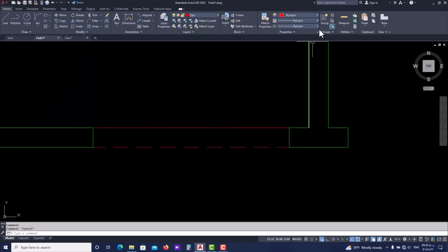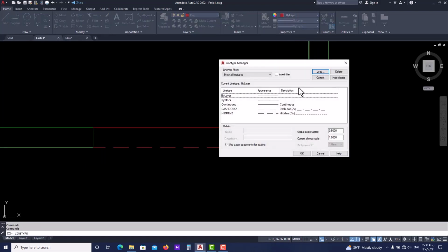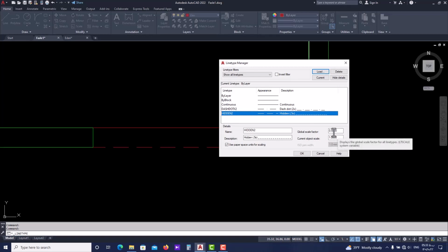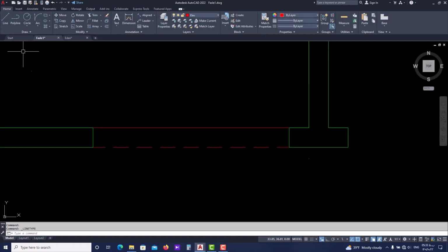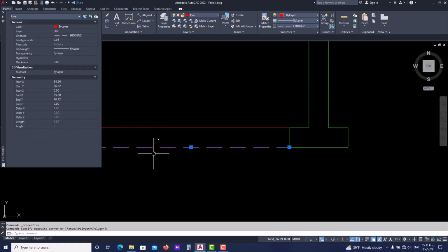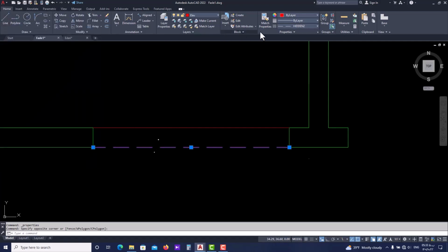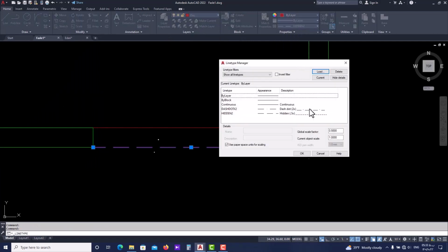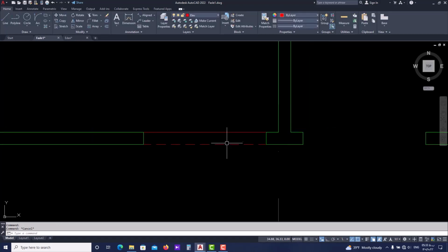And we talked about another point before as well. We said that this kind of scale setting is way different from when you set your scale in global scale. All right, what was the point? We said if you set your scale using Control 1, only the item that you have selected would get changed. But if you set your scale from here in global scale, everything that you draw using the scale would change. And this could have a huge impact on your work and your outcome.